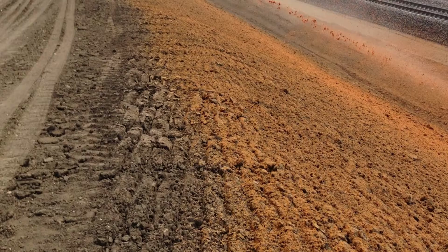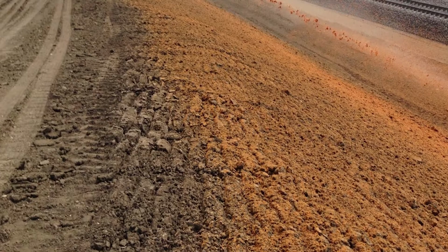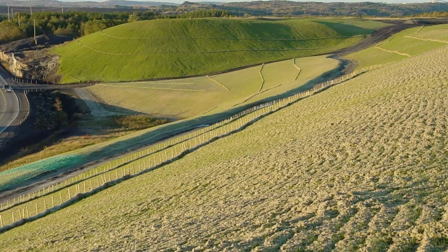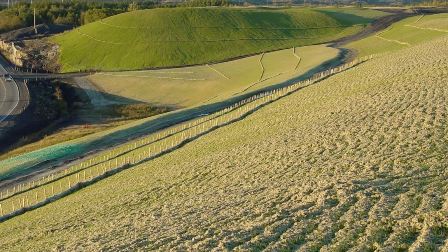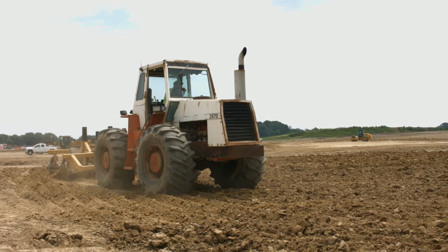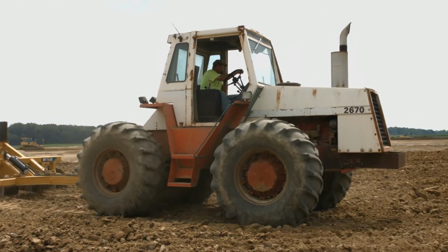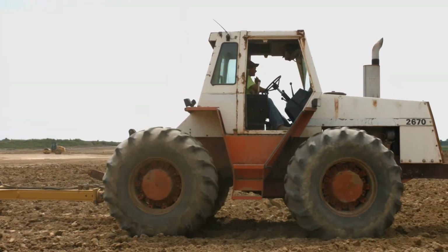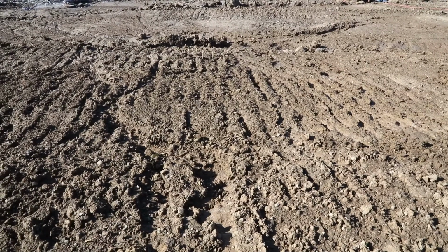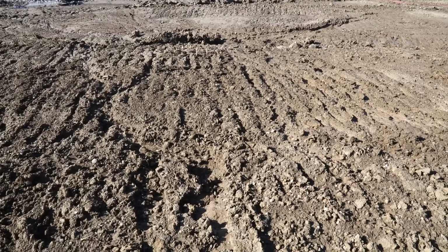How does it work? It protects the soil surface from erosive forces, traps eroding soil particles, enhances vegetative establishment, but not if the surface is smooth and hard, reduces runoff velocity, and increases infiltration. How to install. Use implements that can be safely operated on the slope, for example, disc, tiller, spring harrow, or a front-end bucket loader with teeth, to create a series of ridges and depressions that run parallel to the slope contour as shown in construction plans.